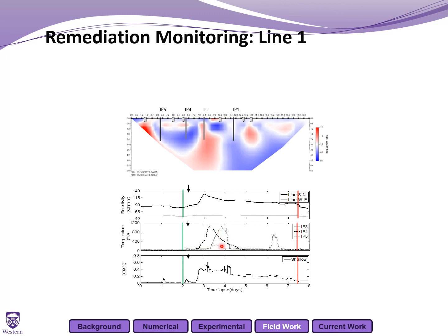And then as the temperature significantly rises here, we end up with that burning off of the water, and that's that corresponding significant increase of resistivity. And then as the process starts to slow down, the temperature, the water cools off, and then that groundwater flows back in, resulting in this slow decrease in resistivity back to initial values again.